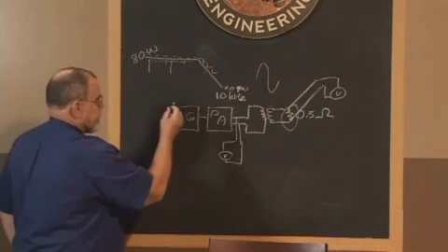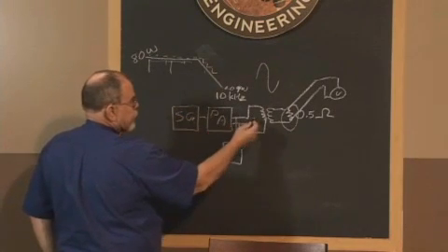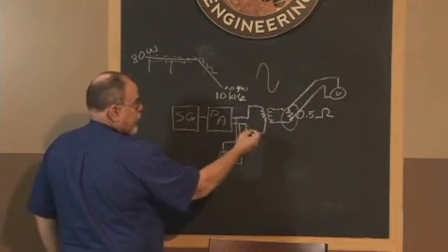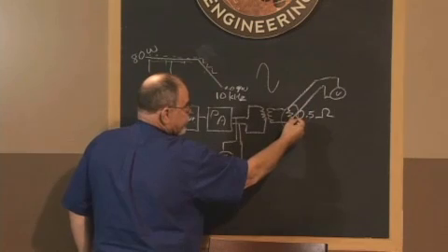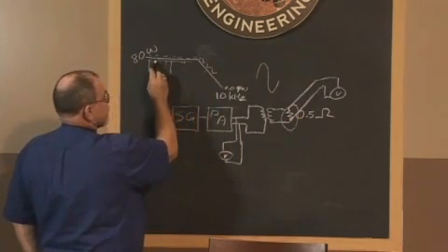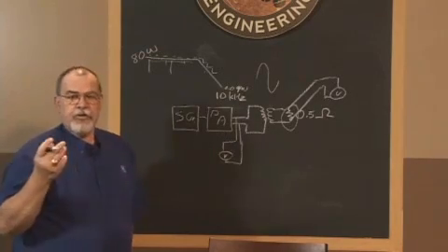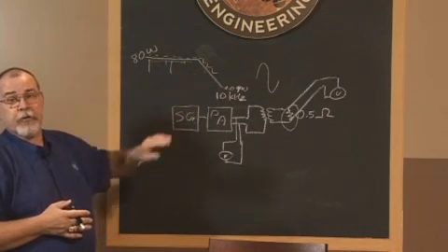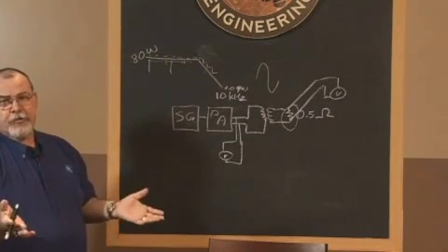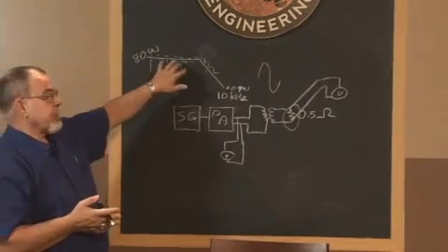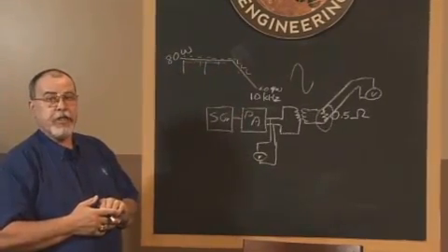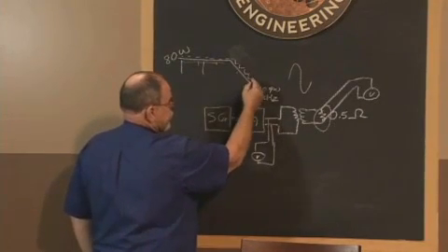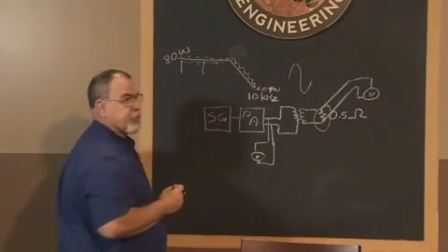So just to recap, signal generator output to a power amplifier to the primary of our coupling transformer. The voltmeter will measure what we're applying. Out here, this voltmeter will measure the voltage associated with this power level. When you do this curve, you want to pre-identify these so you know where your points are. In the real world, we're going to use a spreadsheet or something along that line to calculate these so we know where we're going to be setting things ahead of time, so we can drive this thing properly. But once we get to the end of the test frequency, we will stop this calibration.